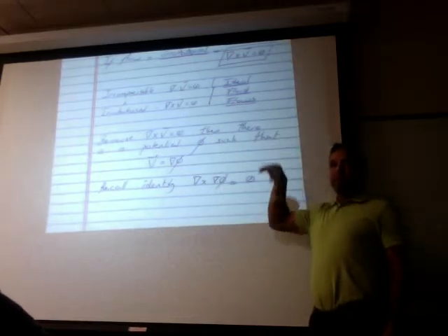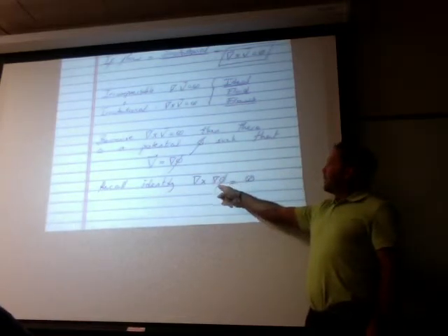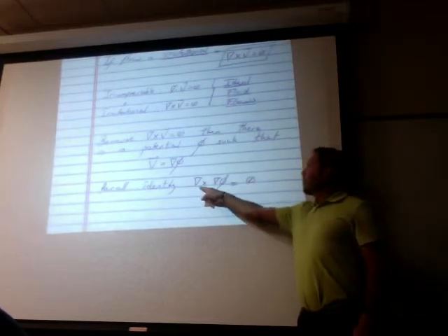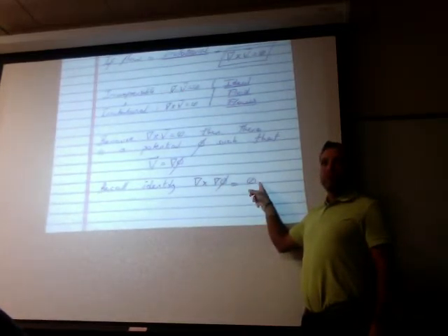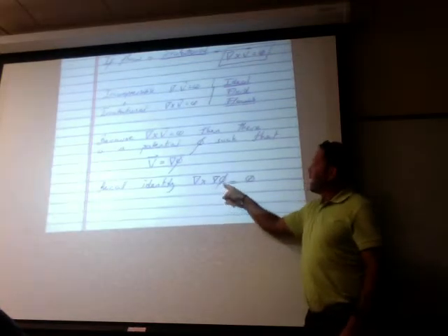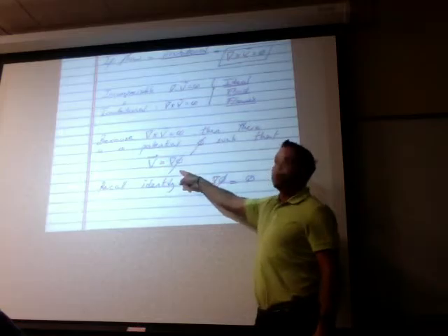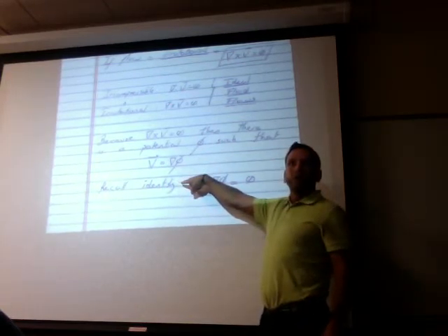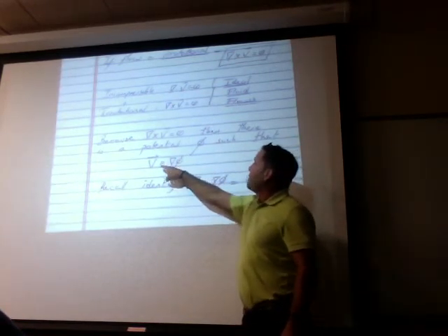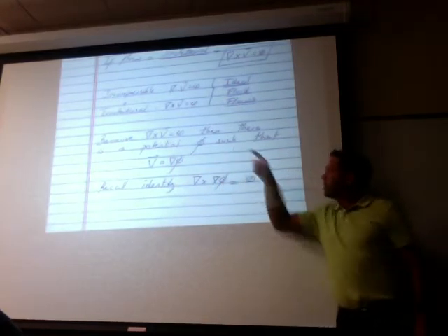There's a mathematical identity, you can prove it, that says if you take any function, whichever one you want, take the gradient of that function, and then take the curl of that gradient, you'll always get 0. We already proved that, right? Now, because of that, anytime you say that a flow field is irrotational, then that function should exist. Now it became a consequence, not a cause. All right? So we can actually define v in terms of that potential because the velocity field is irrotational. Okay.